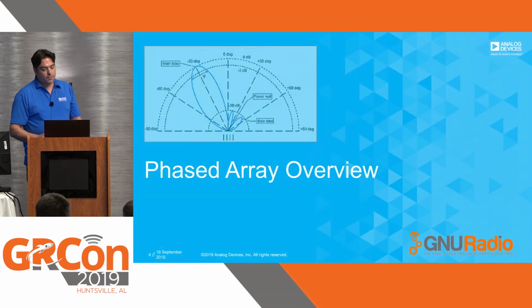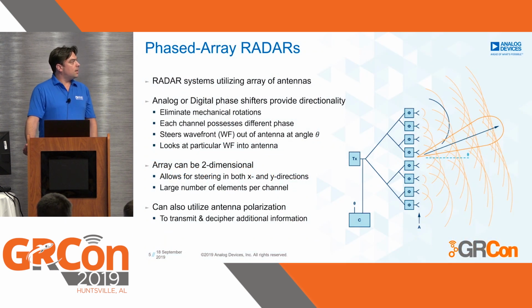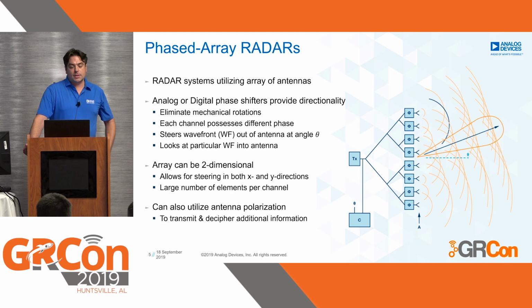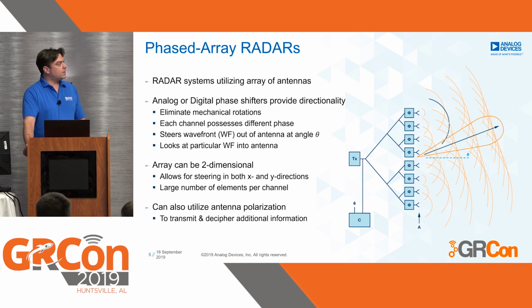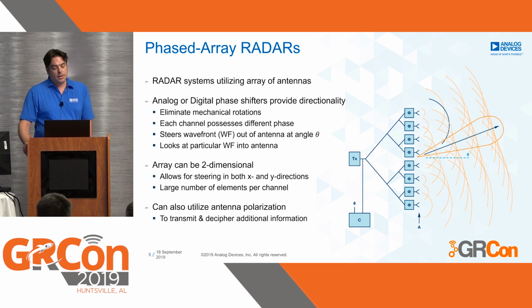I mentioned phased array. I want to give a brief introduction to what a phased array is. Radar systems utilize an array of elements. There are either analog or digital phase shifters, which provide directionality. This eliminates mechanical rotation of the antenna. Typically, each of the channels in this multi-channel system processes a different phase, so you can steer the wavefront out of the antenna at a certain angle.